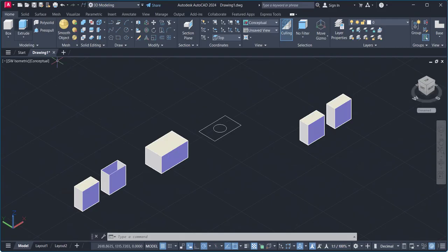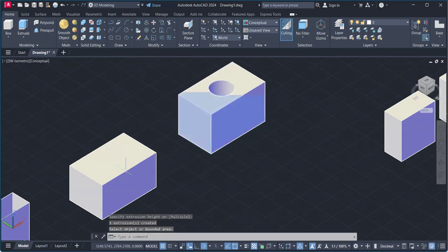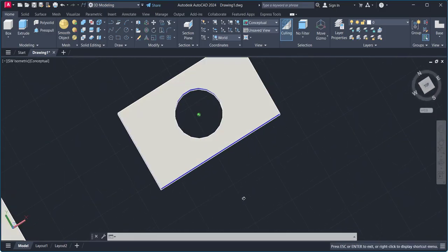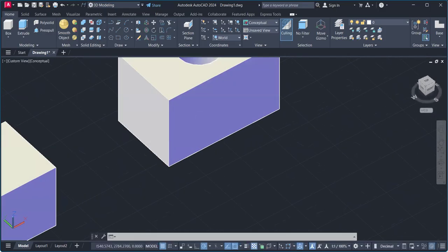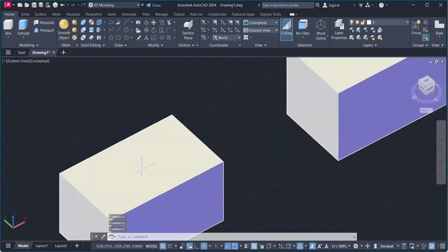And then what you get here is this hollow shape, a rectangle hollow shape, because you select your closed shape area, touching inside the rectangle area. And then you get this type of thing easily. Okay. By use of this Presspull command, you can do it. Okay. Inside the Presspull, we also show about the pull command. This is called a push command. What does the press mean? Okay, we talk about the Presspull here.